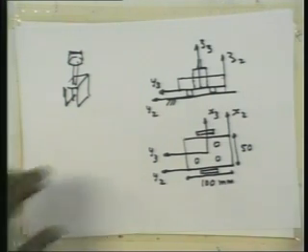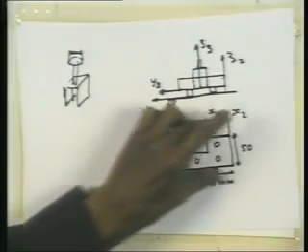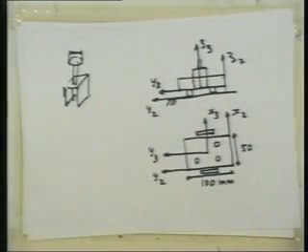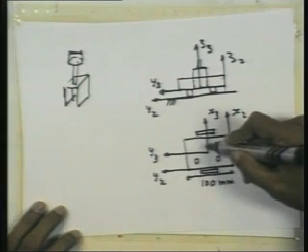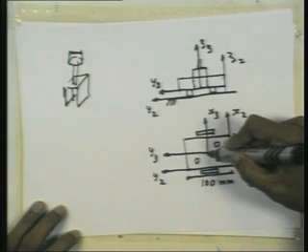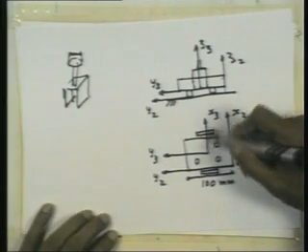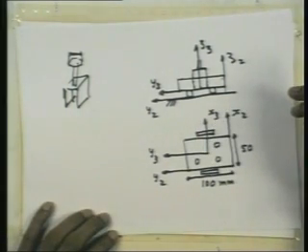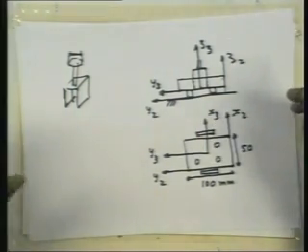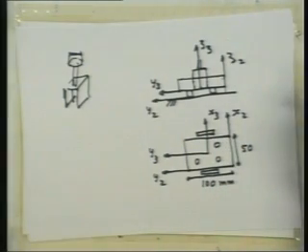So now we can decide what should be the location in this direction to grip the object. What will be that direction? The location of this particular origin, which is a reference frame fixed to the gripper, in this direction is fixed, because if you put it at the center of the gripper, that will be at the center of the object when the gripping is done, right?